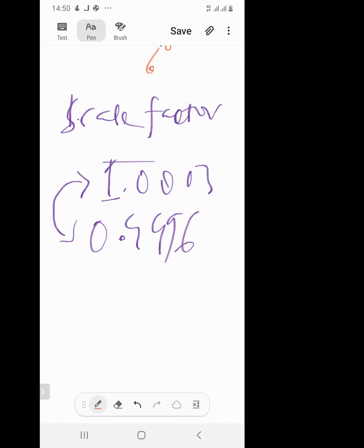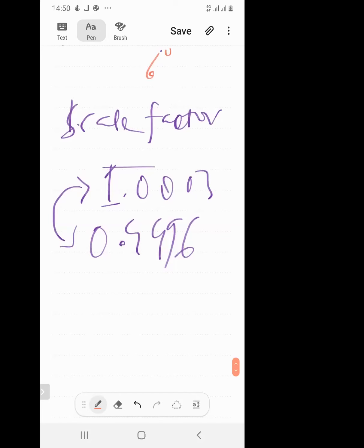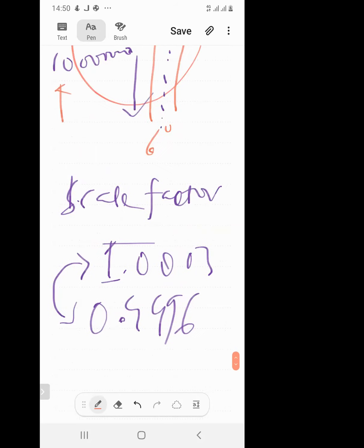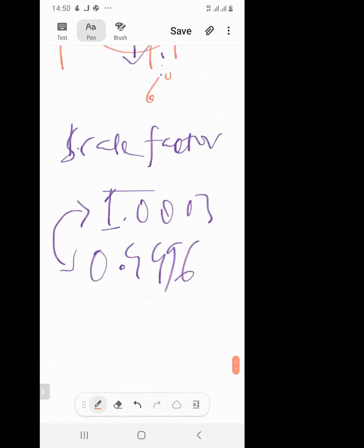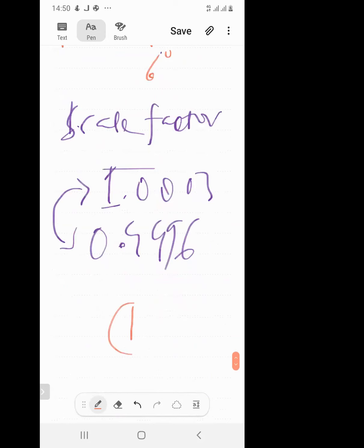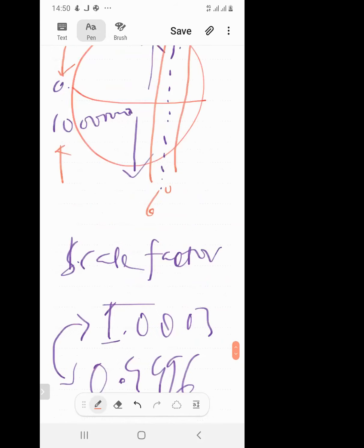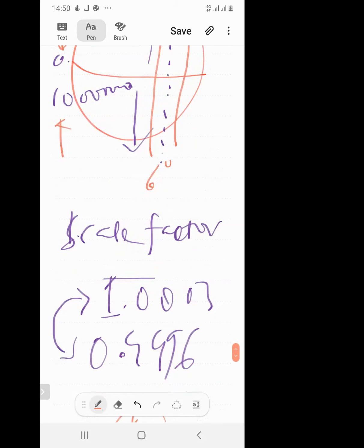Yeah. So these two values, you can see that they are almost the same. They are approximately what value? Look at it well. The two values are approximately the same. One. Yeah, the same. And remember, they are approximately 1. And what did I say about 1 in terms of scale factor? 1 is what you want in terms of scale factor if you are doing any transformation. So the UTM projection does have these interesting characteristics that I want you to know.